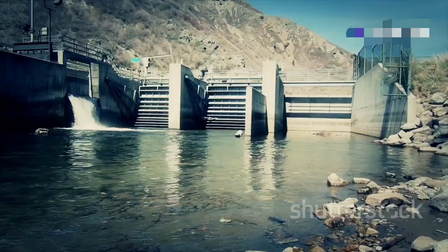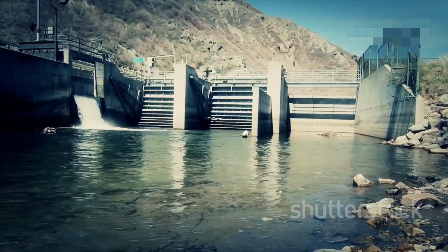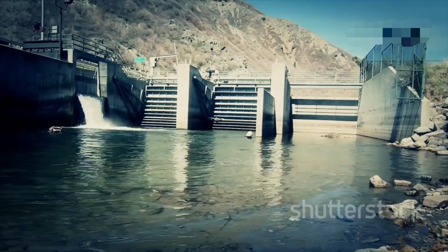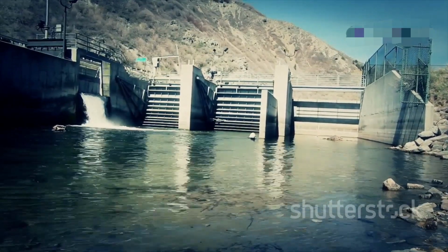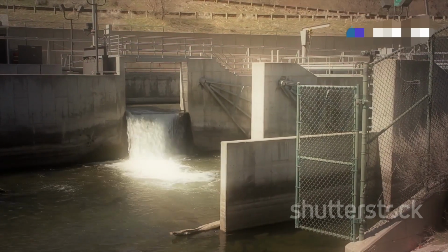The location where piping initiates is important. It could be near a conduit, at the abutment, or within the main body of the embankment, influenced by soil properties and construction quality. For concrete dams, the initiation of a breach is different.